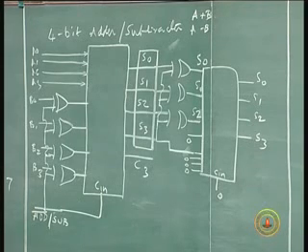Okay, this is the subtractor adder. One other modification of these adders, we have almost completed the adders. We talked about half adders, full adders, multi-bit adders, carry propagation, carry look ahead to speed up, subtraction, complementing numbers, 2's complement and 1's complement.